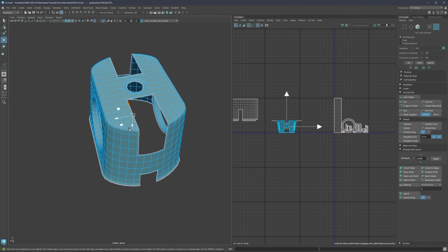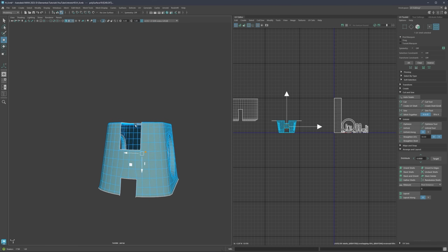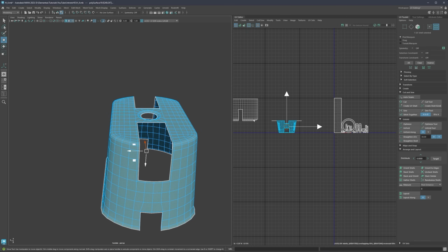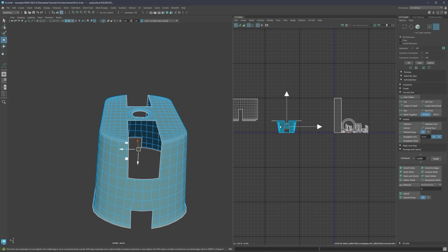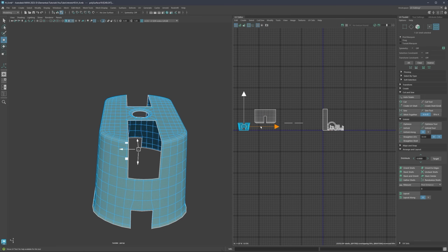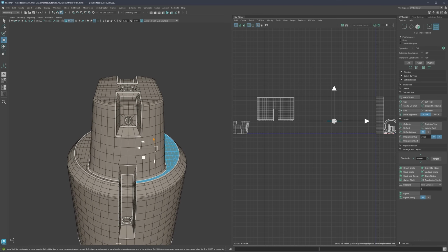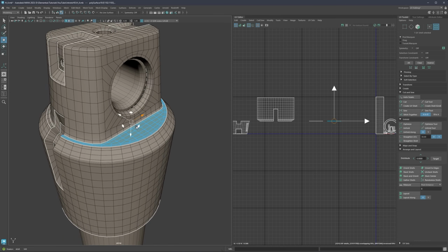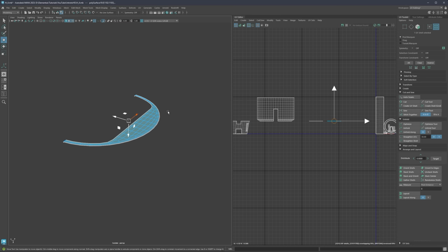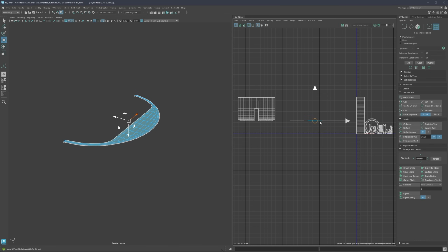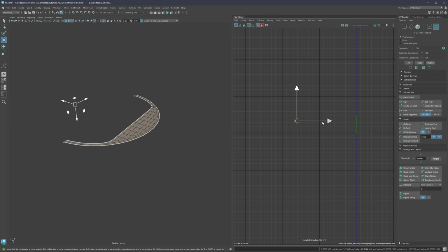So here what we need to do is still again search for the next big angle, which is going to be the angle on the top. So that's also not going to be that complicated. And then let's see the result, what we have here. So I'm just going to select this one and Control 1 and isolate. So this is now our new shell, and we can go simply to unfold, and here too, unfold.